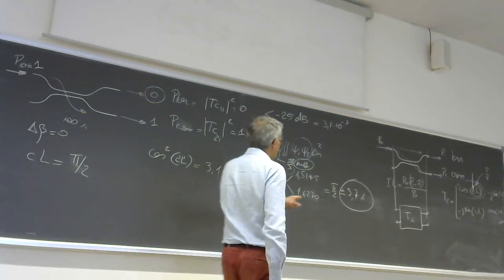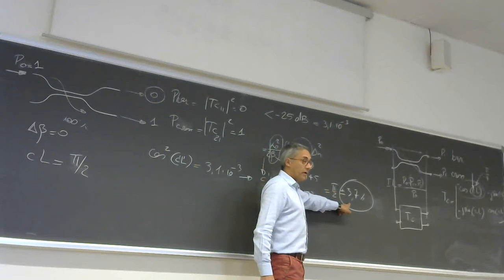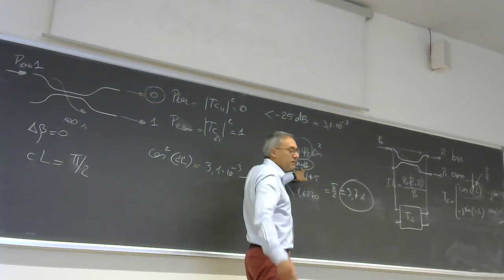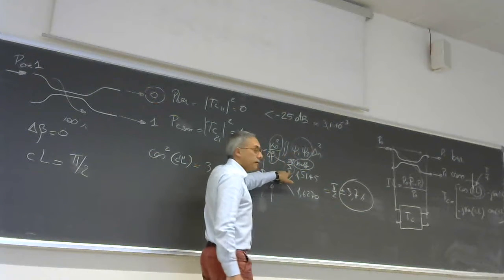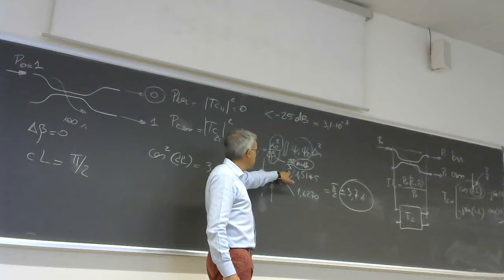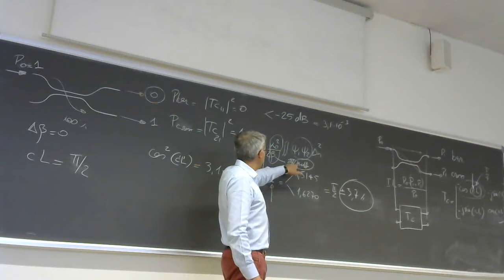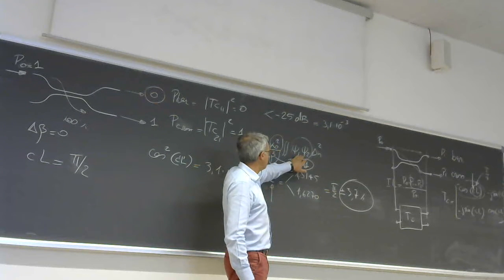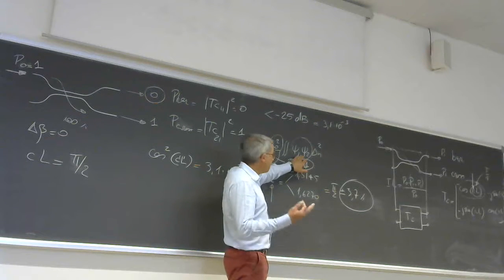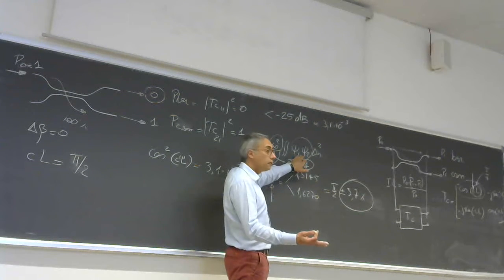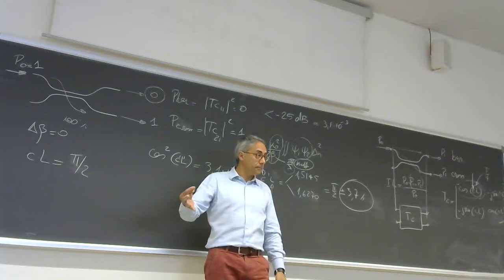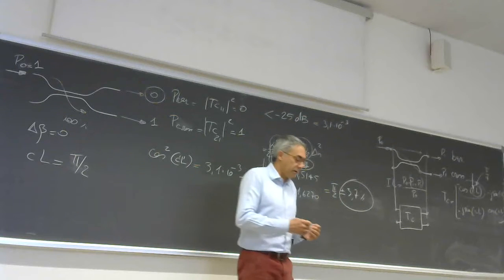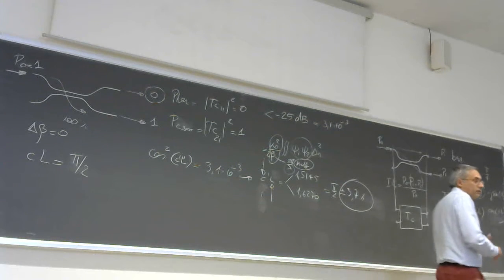Because from this number, you get information on how well you have to control the temperature. The refractive index depends on the temperature. How far you can go in wavelength. How well you have controlled the technology, because the waveguide shape and refractive index are responsible for the shape of the mode, etc. This is, let's say, the difficult part of the design.